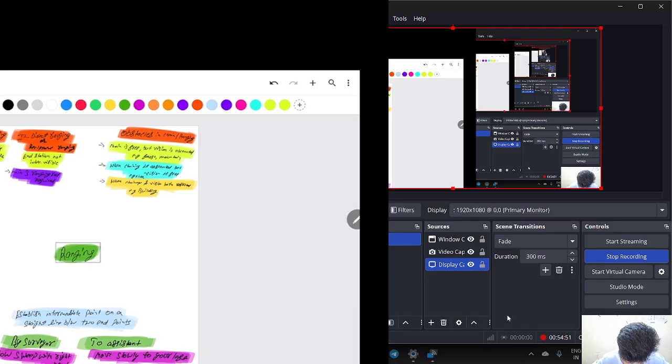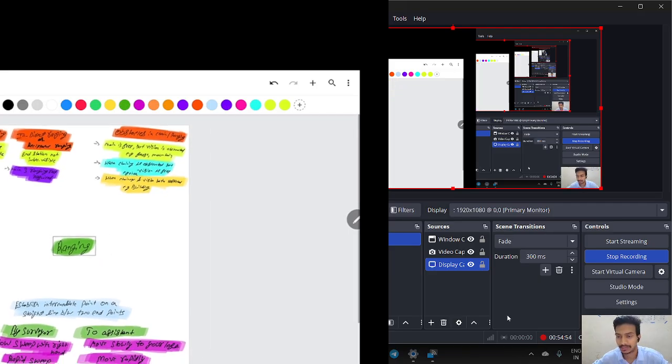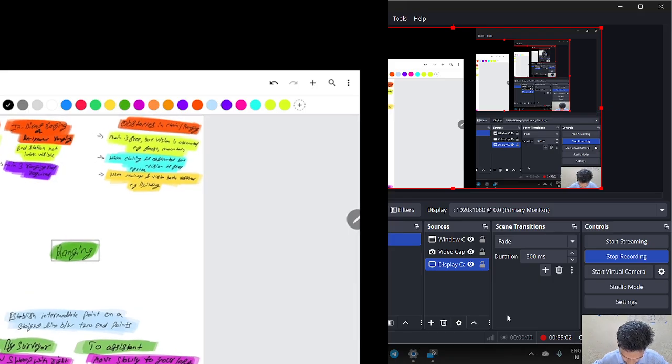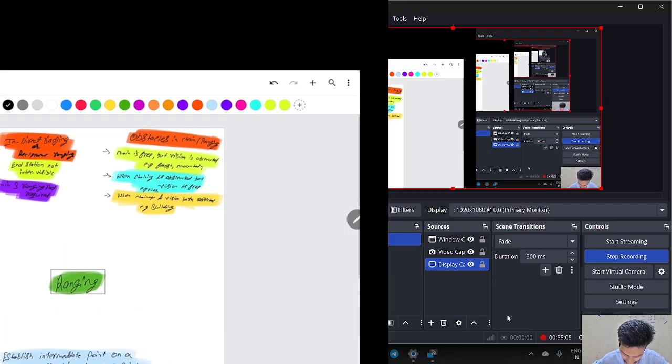Now it's the last of this topic. We are concluding and will summarize. In ranging, there are two methods: direct ranging and indirect ranging. In direct ranging, if the stations are intervisible, a minimum of two ranging rods are required. But in indirect, a minimum of three ranging rods are required for the interpolation. Like station A here, station B here.